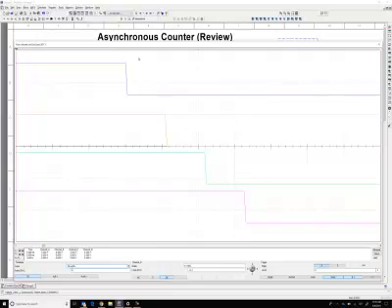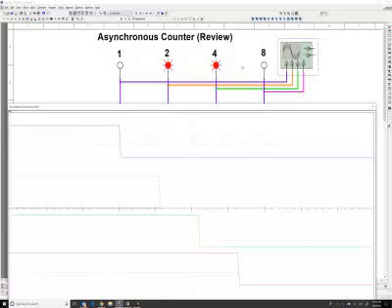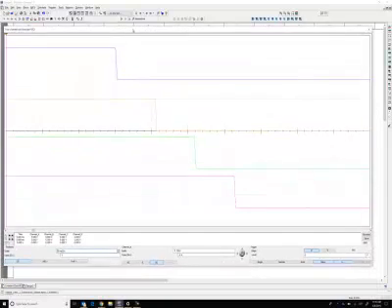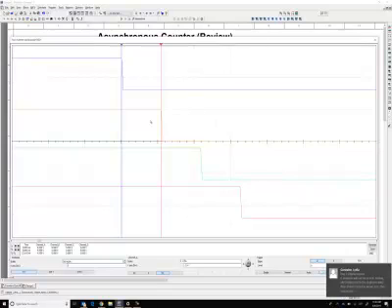If I were to visually just study it, it looks like they're all turning off at the same time, but there's actually a few nanoseconds delay. If I put my time markers, the time between the first flip-flop turning off, or starting to turn off, and the last one is in the 60s or so nanoseconds. I mean, between one bit and another is like 20-some nanoseconds. And it may not be a big deal.